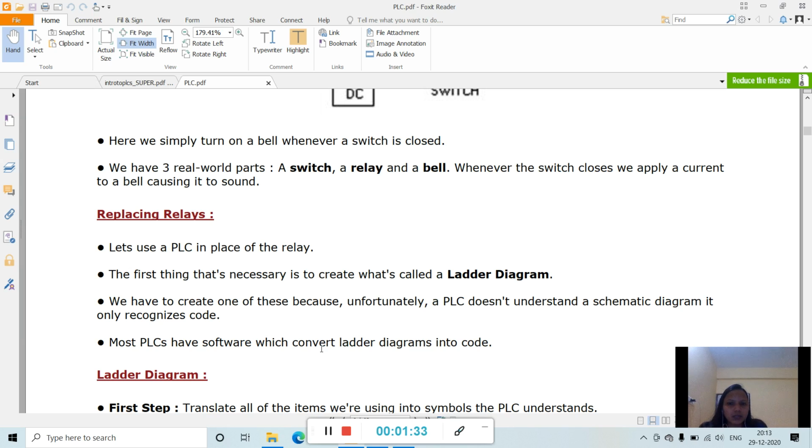So today we will discuss the ladder diagram, and the description of contacts and coils in the normally open, normally closed, energized output, latched output, and branching states. In all these states we will describe the contacts and coils.